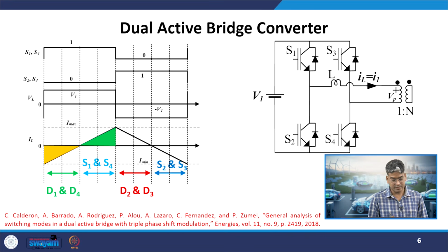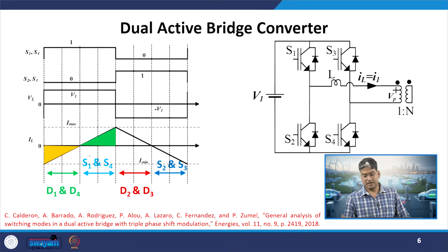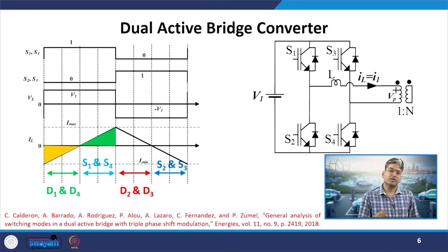So, what is the meaning of that? Suppose we are using this to charge our electric vehicle. If we have a battery bank at the output stage, it will be receiving some amount of charge in one quarter cycle. In the next quarter cycle, that amount of charge will be removed from it. So, the net change in the charge, or net charging effect, will be 0.